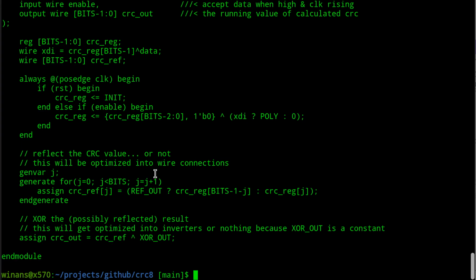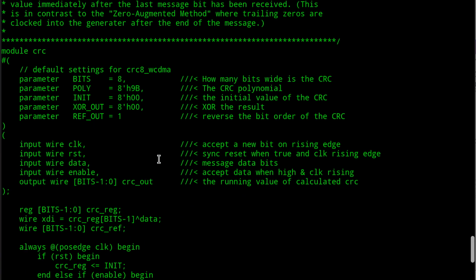So a couple of things hit here, 3 things. First, there are 2 different ways to calculate serial CRCs in general. This is generally how it's done. You have to deal with whether or not the input is reflected, and that would normally be set to the way your natural data arrives in an optimal use of a CRC algorithm.